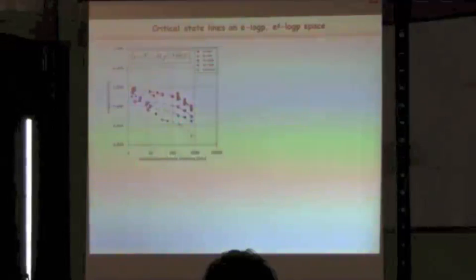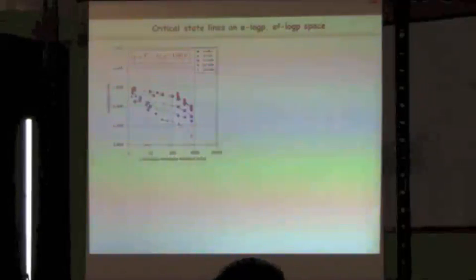This is coherent when we use the global void ratio, because in this case when we prepare the sample and increase the amount of fine content, we decrease the amount of sand grains, which means that when we increase the fines, the void ratio of sand decreases. As below the threshold fine content the main barrier is governed by the sand skeleton, here we have a decrease of the shear resistance.